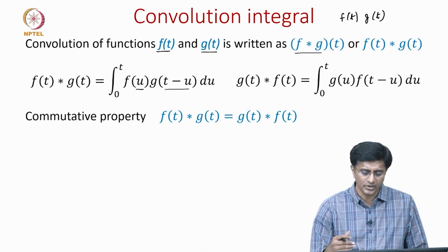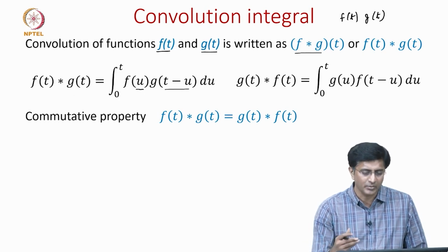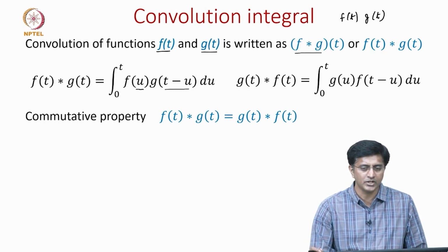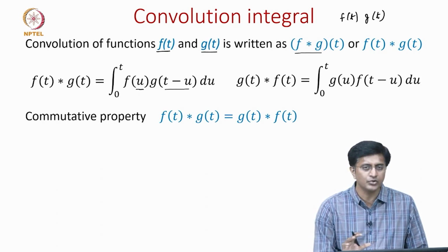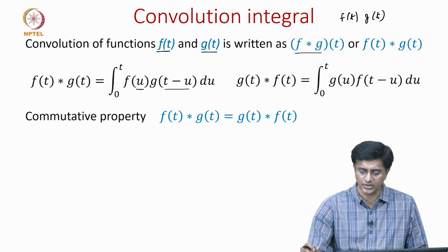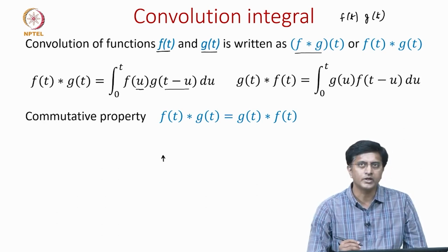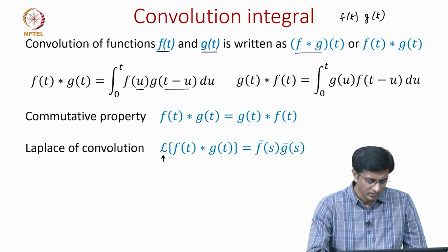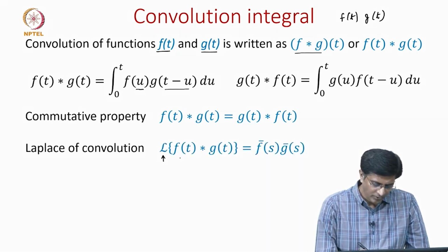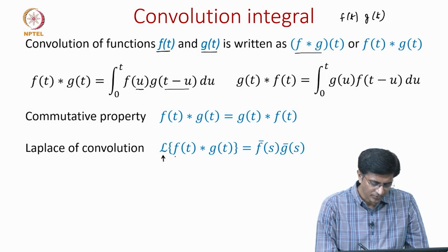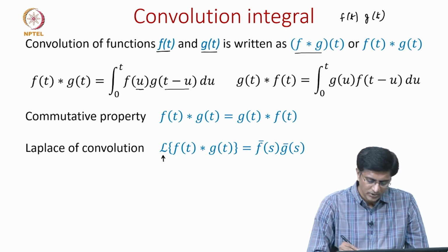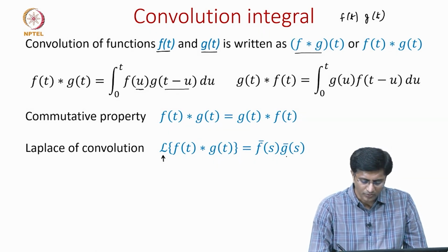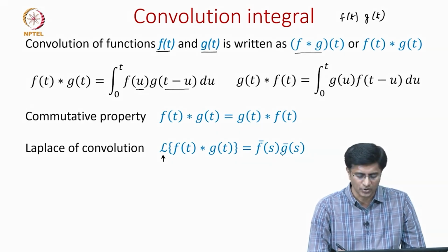This is very important, and we will see, especially in viscoelastic problems, that we come across this convolution integral, and that is the reason why we are reviewing this concept. Now, when we take the Laplace transform of this convolution integral, the Laplace of f convolution g is given as the product of f bar and g bar in the Laplace domain.